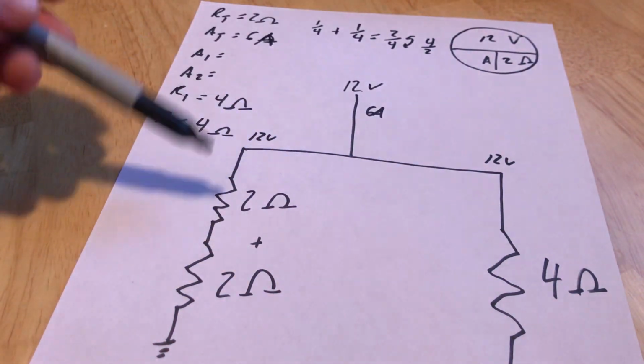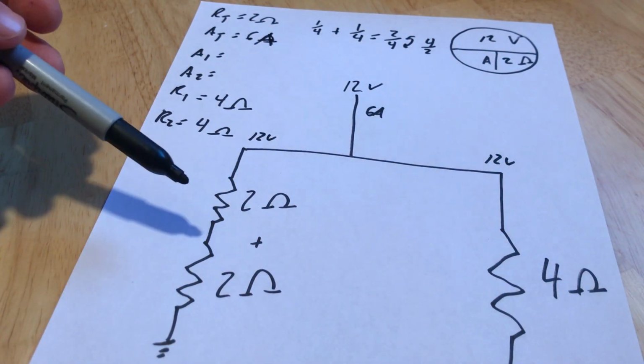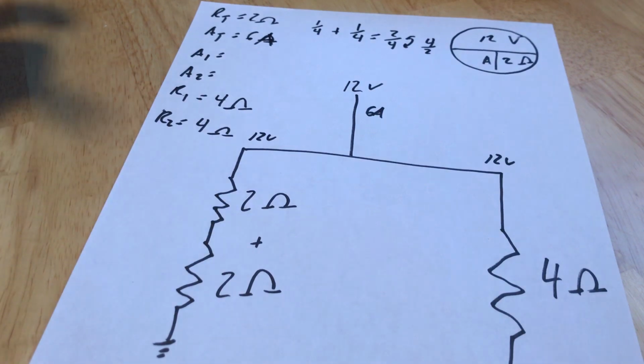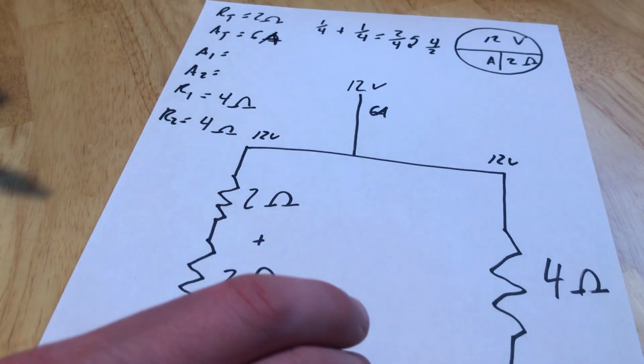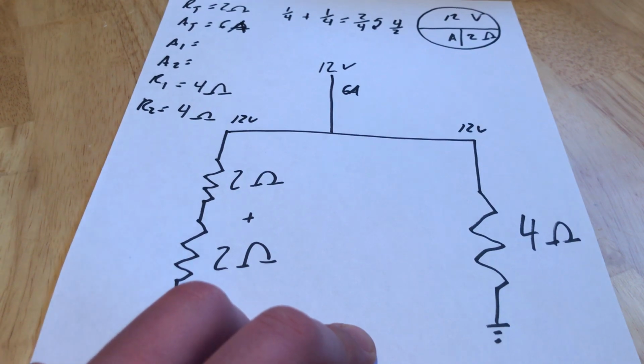And then the fuse next to it might be powering up some of my interior lights or something like that. And those are run in series because they don't have to be that bright. So it's very common to see this kind of stuff. And this is really the way that the whole car is put together. It's just one big, giant parallel circuit because we just have one battery in there. So every single thing that works off of that battery is in parallel with the other circuits.